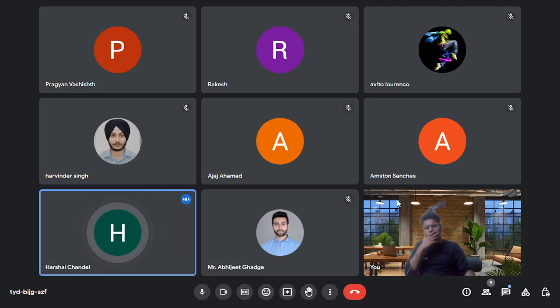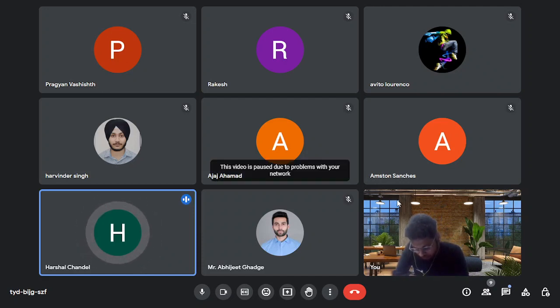You have the X-ray tube emitting radiation. When you pass the X-rays, the film below the metallic plate which you are inspecting records the X-rays that are falling on it. So if there's a crack, the X-rays will come through with more intensity, and you'll get a spot where the crack exactly is. It's like when you have a crack in your hand and you take an X-ray. It is similar to that.